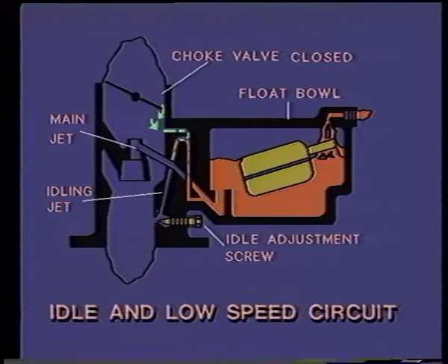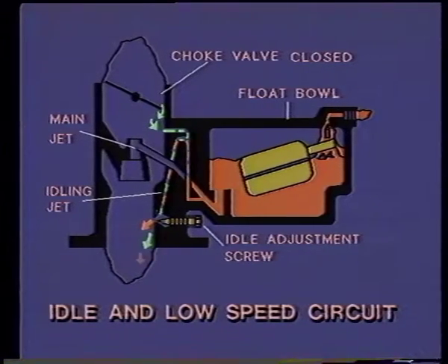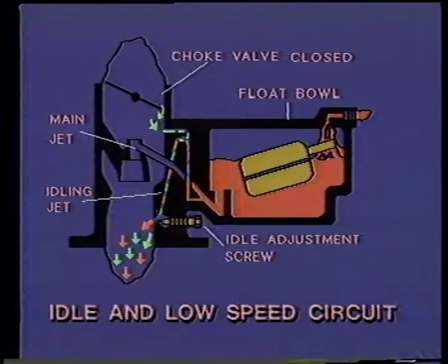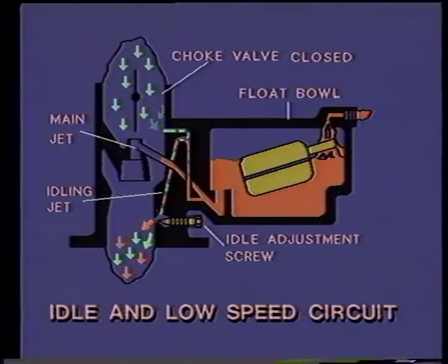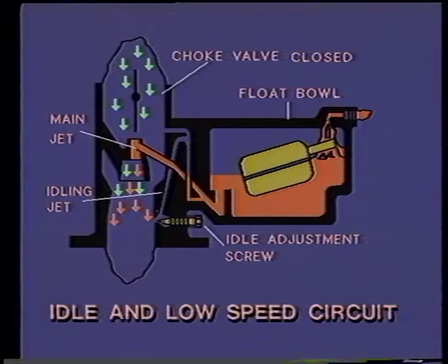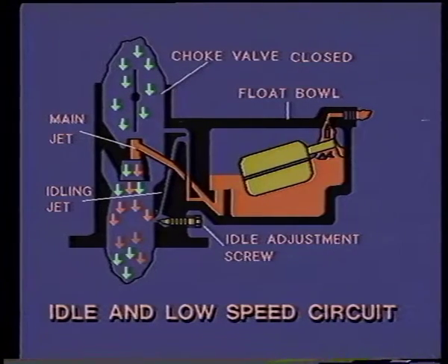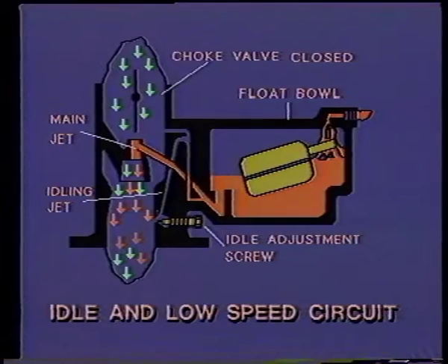In such carburetors, the takeover by the main jet from the slow-running jet can occur smoothly, since as the velocity of the airflow through the venturi increases, so also does the depression over the main jet until it exceeds that over the slow-running jet, which therefore can no longer deliver any fuel.